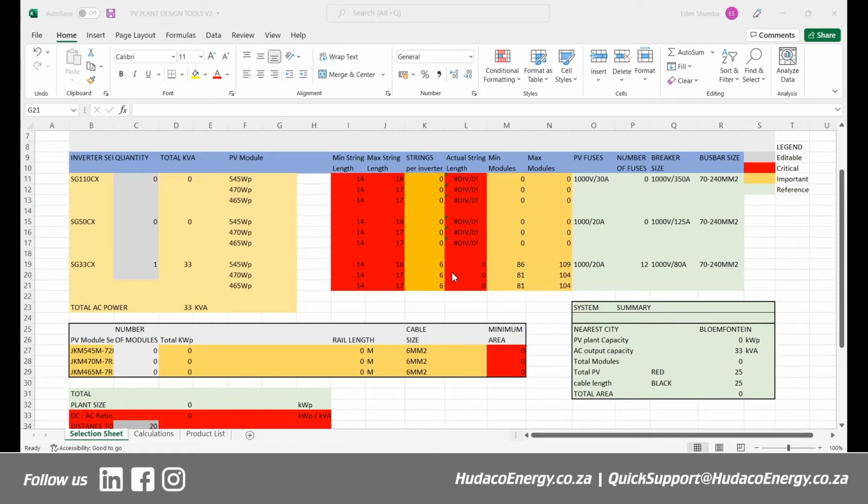Now, remember, this is just a range of values between 81 and 104. We want to see if I were to choose 81, for example. Let's say, because 81 is for 470s and 465. Let's say I'm using 470, right? And then I put 81 panels. The system tells me immediately that this will amount to about 38.07 kilowatts peak on the panel side.